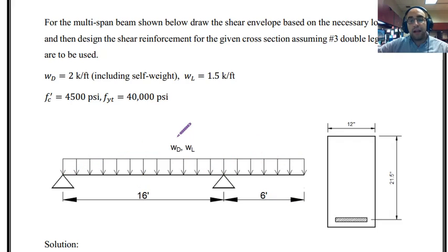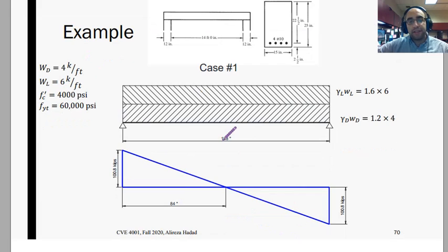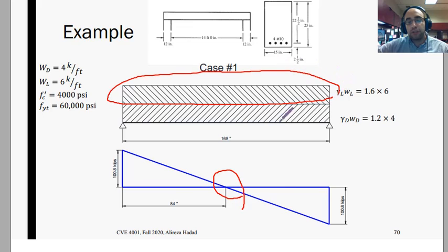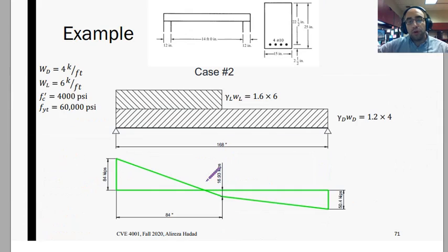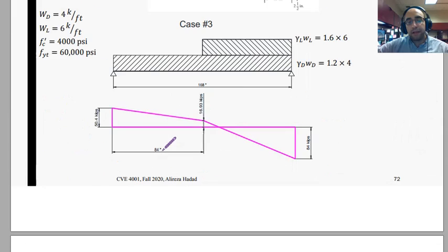influence line analysis and how it is used for finding the maximum moment due to changing loads or live loads on structures. Over here, we have a beam like this, and from the example that we solved during the class or during the presentation file, we saw that at the middle of the beam, we have 0 shear force. And since it is 0 here, just based on considering live load covering the whole span, I consider 2 other cases, live load only on the left span and only on the right span, to get the positive and negative shear at this point.